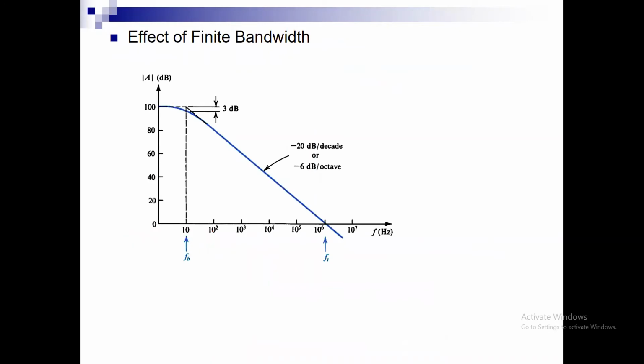Now, one more thing that we add to the formula is that I have my op-amp, it has an open loop gain A, this is the open loop. In reality, any circuit that I design, this has to be A of S. Okay, so whatever I design as A of S will have a finite bandwidth.